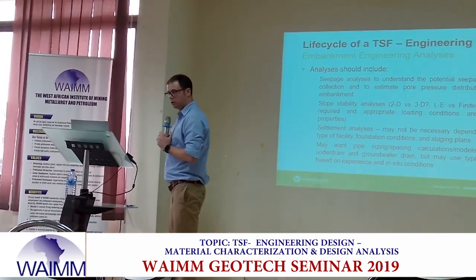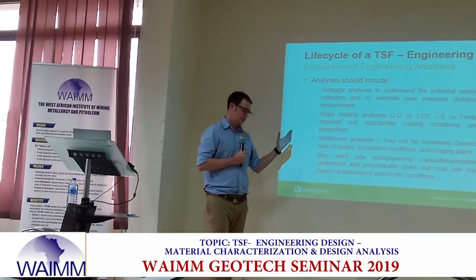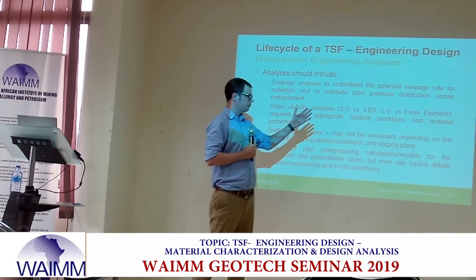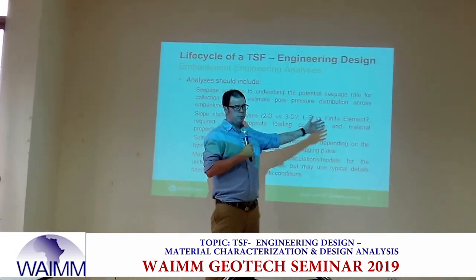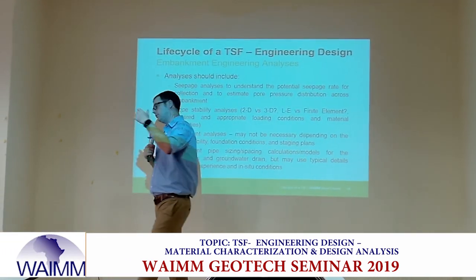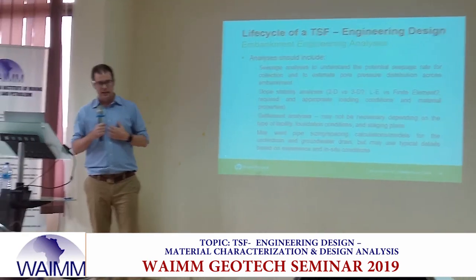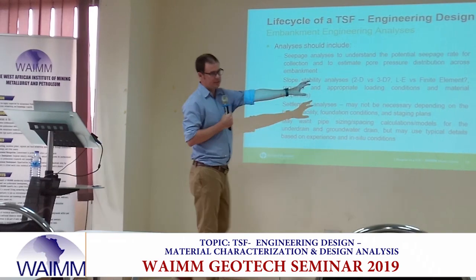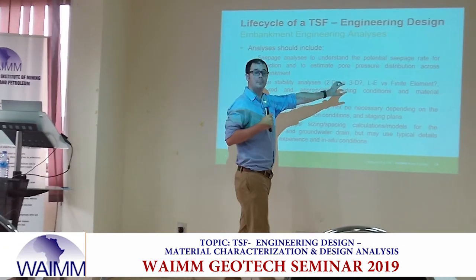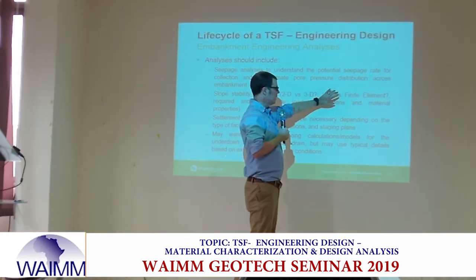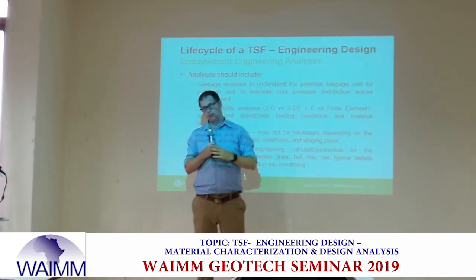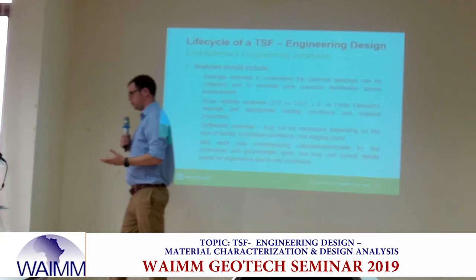There's also what's called limit equilibrium, which is the current standard of practice for slope stability. Or do we need to go into numerical modeling, finite element modeling, finite difference modeling? Again, my opinion is that limit equilibrium is typically conservative, or should be done in a conservative way. And as long as we're properly accounting for material behavior, it should be sufficient.